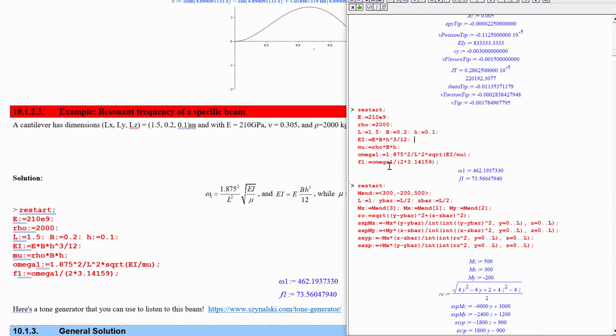If you hit it in the right direction to excite this thing, then you'll hear that 74 hertz. What if we had it oriented the other way? Now this is going to respond with 147 hertz. So the fundamental frequency is the lowest frequency that the beam is going to be able to respond to. And for an arbitrary setup of the beam, if you don't know which way is the thickness direction, the fundamental frequency will correspond to the minimum thickness, because that's what's going to give you the lowest frequency.